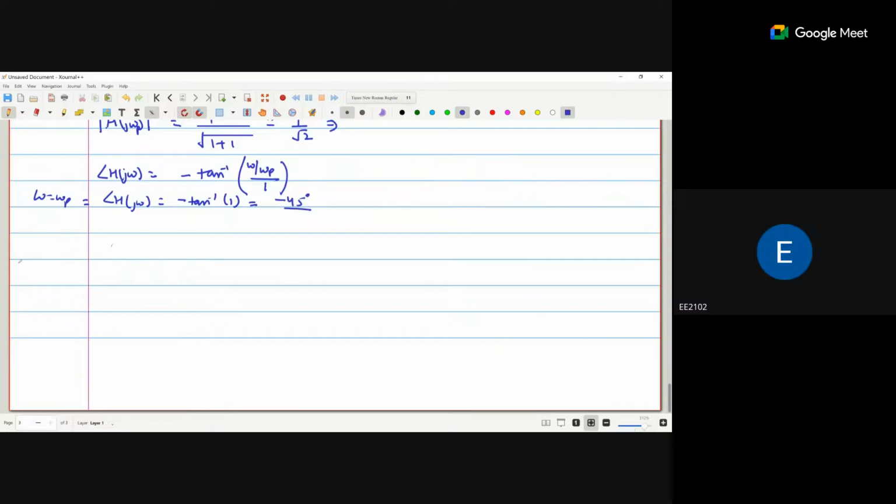Now if we are going to implement that, we have one R and one C. This is grounded. Input signal Vi, and this is the output signal Vo. So can you calculate the transfer function, Vo upon Vi? What is Vo? The voltage across this capacitor, 1 by Cs. That is the Vo.